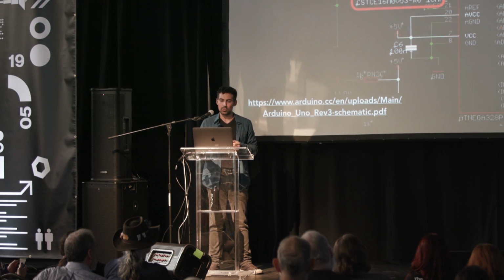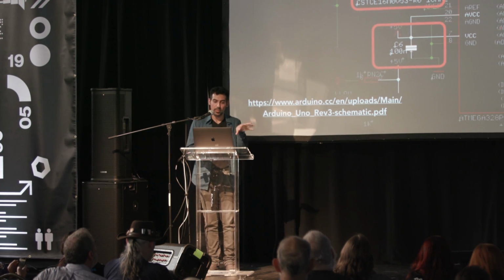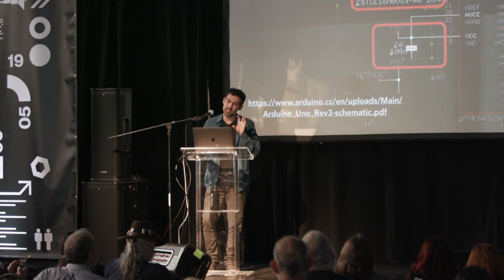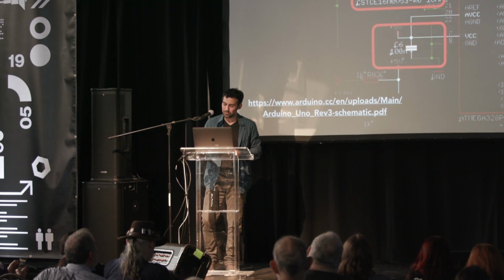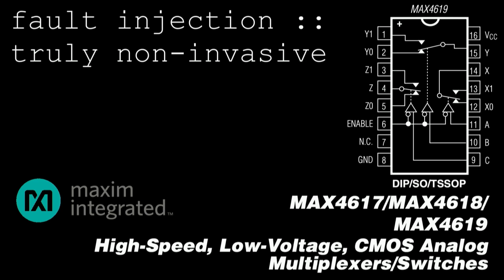Normally you either have to modify the crystal and actually provide your own clock, or you have to remove the bypass capacitors around the microcontroller, because the capacitors are storing all this extra energy. Well, what we want to actually do is a truly non-invasive attack. So far we've been talking about primarily non-invasive attacks where you don't actually have to modify the IC itself, but really you do have to modify the PCB. I think that is somewhat invasive if you're removing screws and breaking plastic and sitting outside of someone's hotel room trying to work with a PCB out there.